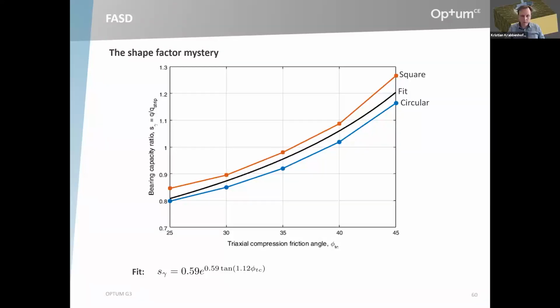So the plane angle being 1.12 times greater than the triaxial angle, you would then get these results here. Of course, in the strip calculation, or plane strain, you use the plane angle in a regular Mohr-Coulomb type analysis.